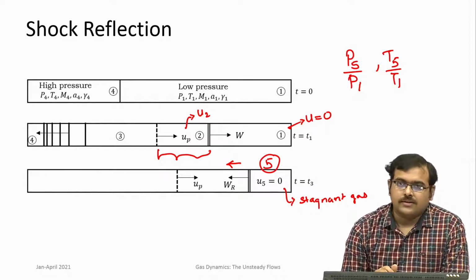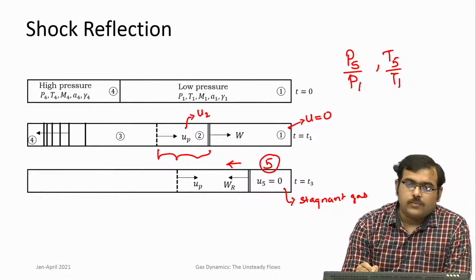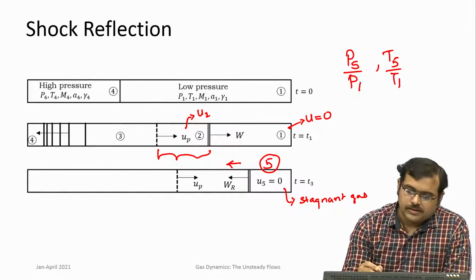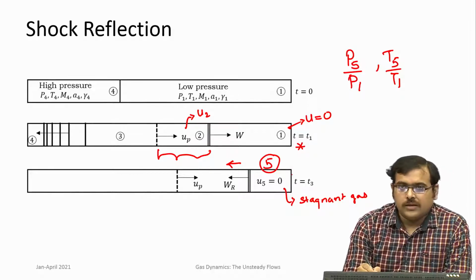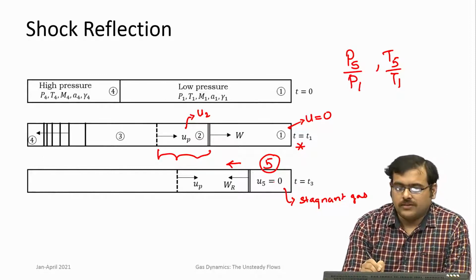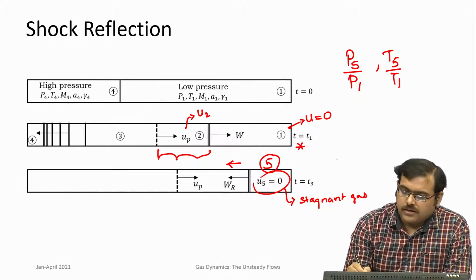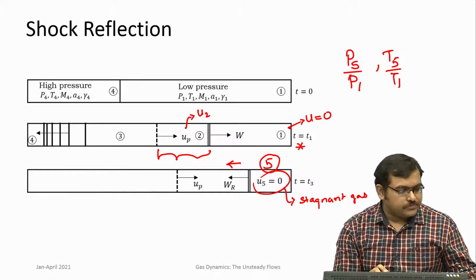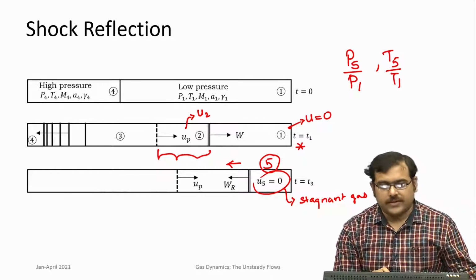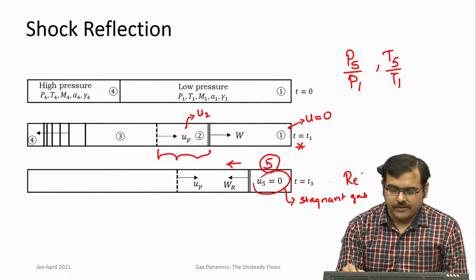So that is the key point here, but they can produce very high pressures and temperatures. When you need much higher temperatures and pressures than what is produced in this scenario, we can use certain devices so that a reflection of the shock is produced, and this stagnant gas after reflection is of much higher pressure and temperature that can be used for other certain experiments. So both kinds of uses are there. This kind of operation is known as reflected mode